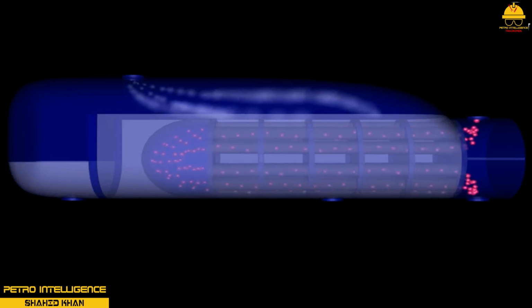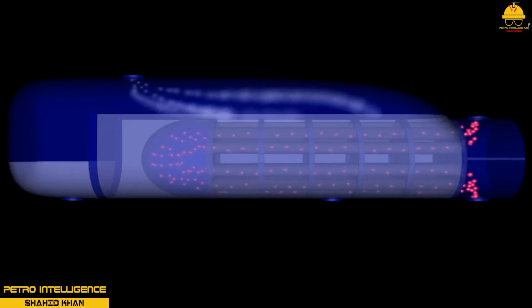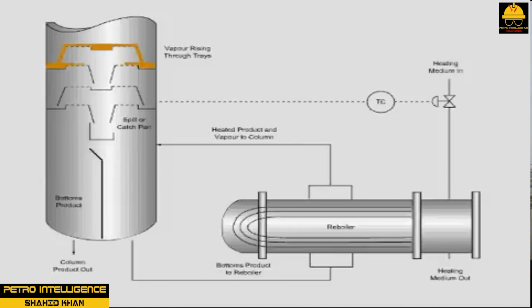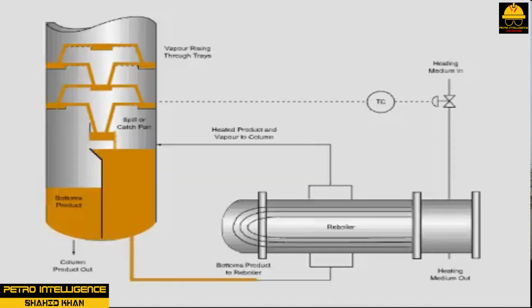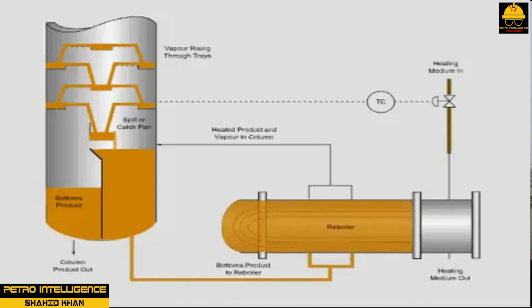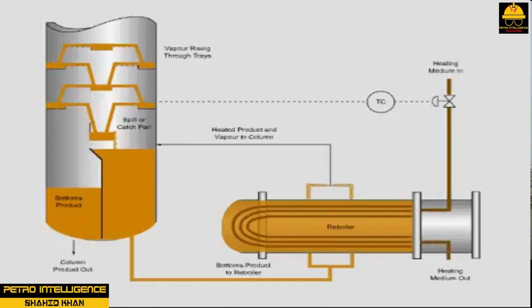An important concept with a distillation column is energy or heat balance. Reboilers are used to restore this balance by adding additional heat for the separation processes. Bottom products typically contain the heavier components from the tower. Reboilers take suction off of the bottom products and pump them through their system. Column temperatures are controlled at established set points. Product flow enters the bottom shell side of a reboiler.